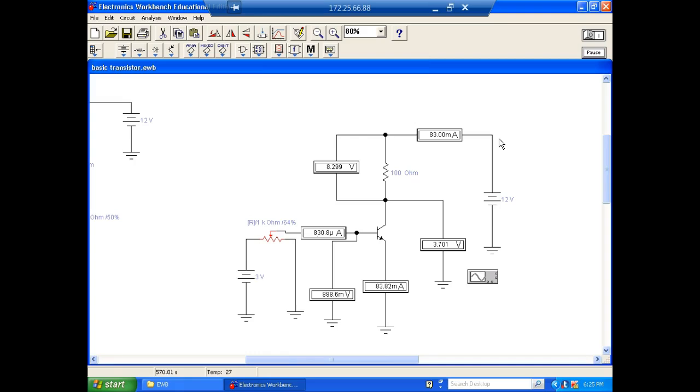But ain't that neat? Good gracious, you can almost see this now. That's 100. So this transistor has a gain of 100, which means that for every milliamp I put into the base, I would get 100 milliamps out. Now this is still what we call a small signal transistor. I couldn't put 1 amp into it and get 100 amps out because this little transistor just wouldn't handle it. But we do have transistors that can handle that. Usually those have a lower gain. So your big power transistors will have a lower current gain.